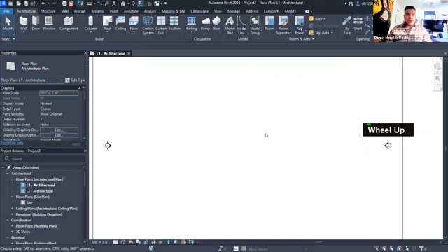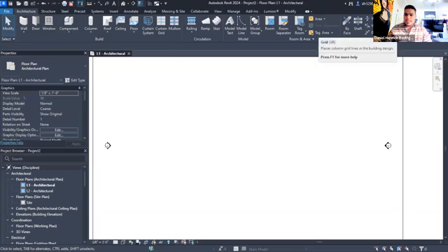First thing that's very important with every project are grid lines. Both structural and non-structural components can go into these grid lines. They're very helpful to make sure that all your measurements are correct within your drawing. So this is the first tool that we're going to be using. Right on the Architecture tab, we're going to go to Datum, and it says Grid here. And that's the tool that we want, okay?